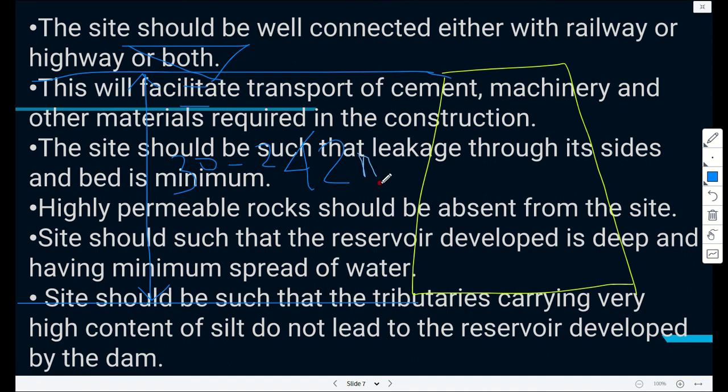You can calculate the pressure. These are the driving head. So the driving head means this water is in a hurry to escape to this side. So that means this dam, or the impounding structure, has to be designed properly, because water will try to escape as much as possible, from the bottom or within the dam itself. So you can imagine if there's something permeable, that would be kind of a weak point.